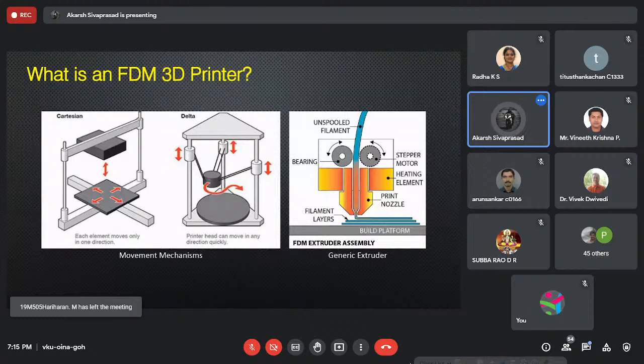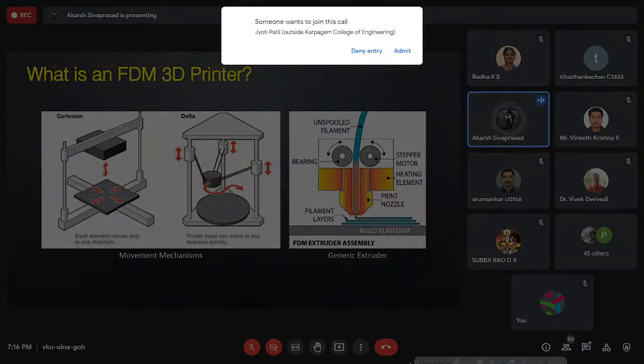As I said, the nozzle is not a fixed element. You can change it to whatever grade or dimension you want. There are filaments now which are composites, with chopped carbon mixed in. Those have really high abrasion, so you probably need a quartz studded nozzle. You have a brass nozzle with a quartz crystal in it, with a pilot hole drilled for the same diameter. You force the filament through the quartz, which is much harder, so it takes up all the abrasion from the carbon or whatever composite you add.